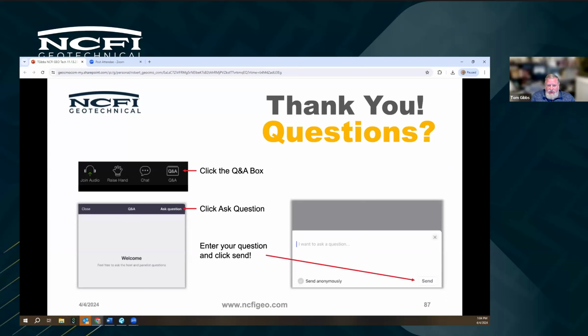Rarely are we dealing with situations where we'd have to go that deep. You have to think too about what you're trying to support. Is the load big enough that you need to go that deep? Typical deep injection projects, though, maybe I should say atypical. Some projects I've been involved with and have heard of, and know some of my colleagues have done, definitely down into the 30, 40, maybe even 50-foot depth for deep injection without any problems. It's really more about having the equipment to get the delivery system in place.